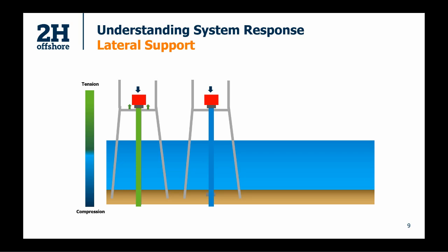We're still looking at a system that's in compression, and the susceptibility to buckling is a factor of the compressive force, but also the span that the conductor is covering, essentially from the mudline to the deck. So if we're worried about buckling, the easiest way to negate that is to reduce the span so that we're back to a point where we're not worried about buckling occurring.